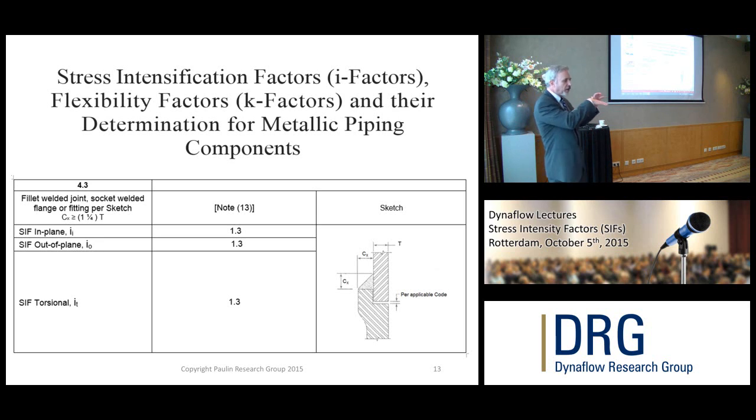I think that's important. So I think you'll be able to go in, look at the document and say, I want to run a finite element calculation. This tells me how to do that. I want to run a test. This tells me how to do that. So you know exactly what to do to get the right stress intensification factors to use in the code, so that you maintain a reasonable safety factor, not something gross.